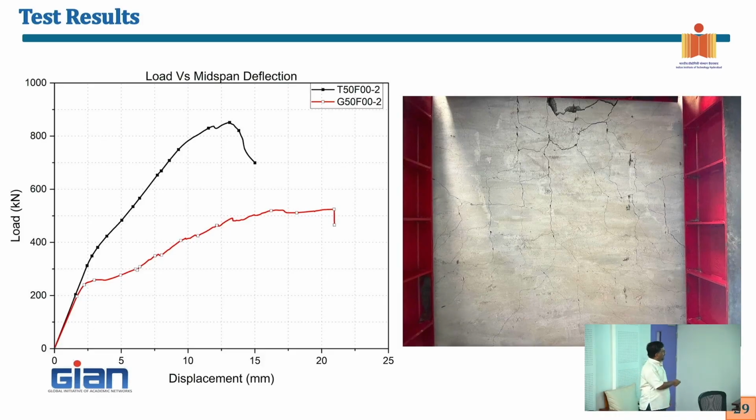But having said that, the design loads are never going to be more than 10-20 kilonewton per meter square. Of course, this slab is for an elevated slab, and this is the worst condition that you can assume. This can be used for deck slab also.